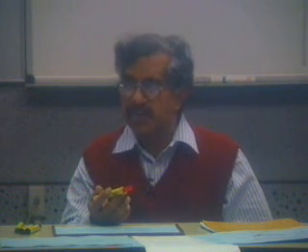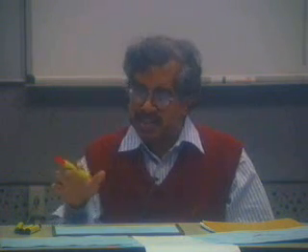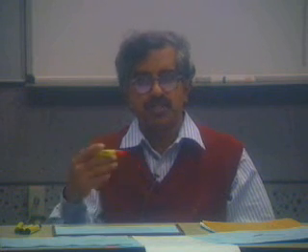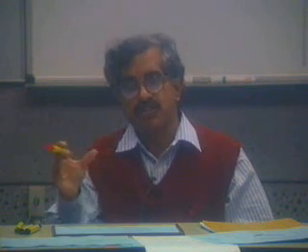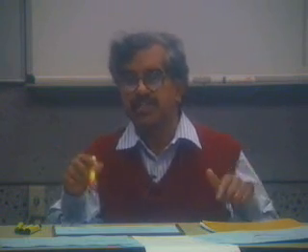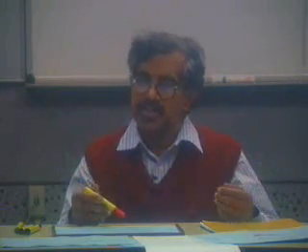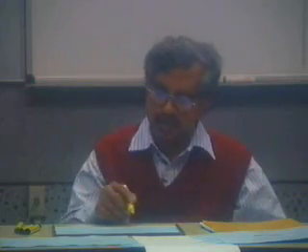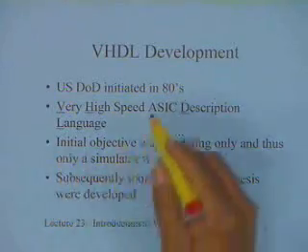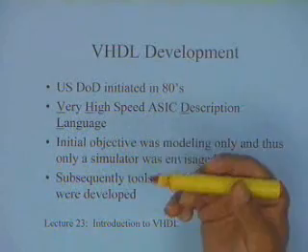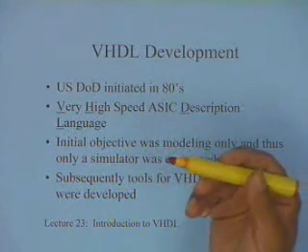For complex systems, there is no other way but to go in for a standard description language, where the semantics are very clearly laid out, and which should be able to specify not just the functionality but also the timing relationships. Functionality in totality implies the timing relationship between signals and so on. So that was the basic motivation behind developing a hardware description language.